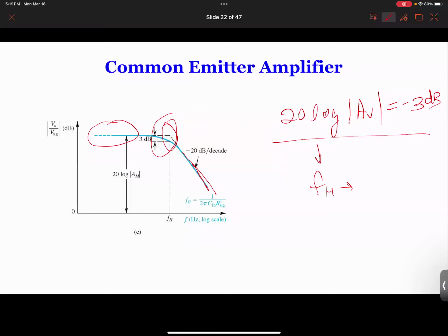And secondly, when you have such a large band, you might accidentally amplify some noise that you didn't want. So if your signal is here, but the noise is here, you want that noise to be attenuated, right? But if you design your circuit with such a large band, here, yes, it gets amplified, but the noise also gets amplified. Now you have trouble because the noise is also there and here.